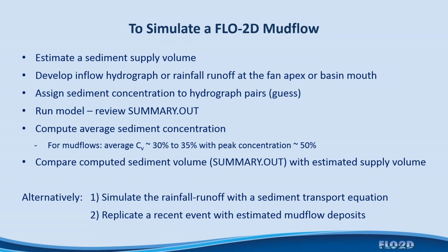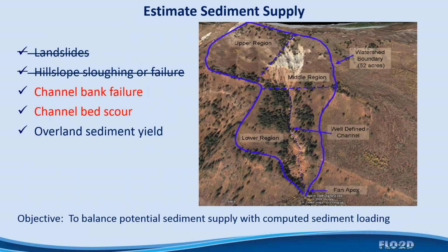What you have to remember, though, is that everything that's run off the fan and down into a river channel somewhere, or just out onto a peneplain or wherever the flood eventually has dissipated to, you're going to have to include in that runoff amount a sediment concentration by volume, so that you account for that amount of material that's not in the deposits on the alluvial fan.